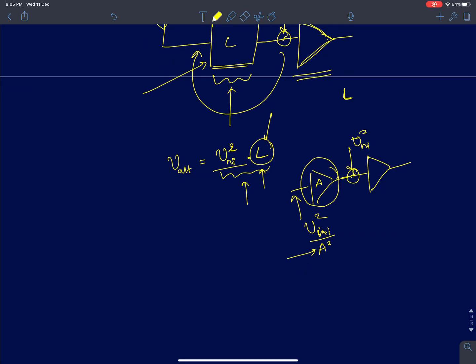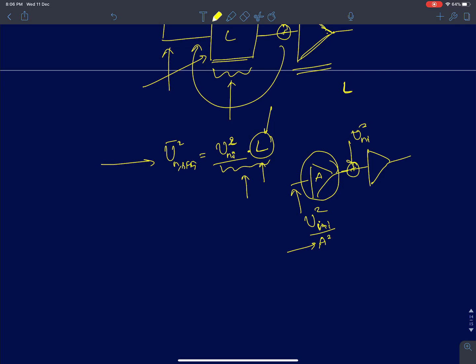Okay, so your output power will be, this is out square noise at the outputs, or rather, noise input referred to the bandpass filter input. So the noise at BPF input, I square, will be this. Here I've assumed the bandpass filter is noiseless. That's the assumption. I haven't included the bandpass noise. You'll also have to include the bandpass noise and all that.